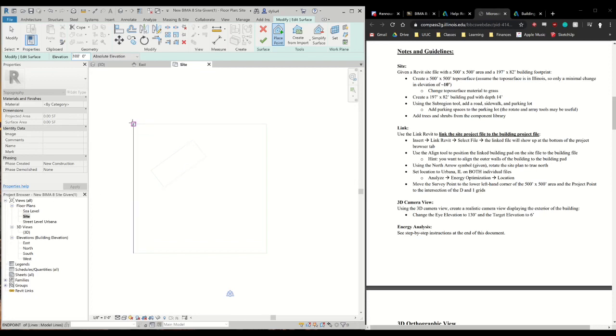So I'm going to first define the corners of my box. I've given you these green rectangles as reference points. So I can click 1, 2, no surface is appearing, no line is connecting these. Why is that? Well, a topo surface is a plane, so it takes 3 points to define a plane, 4 points to define our nice square.